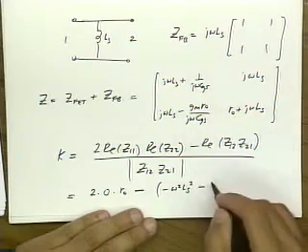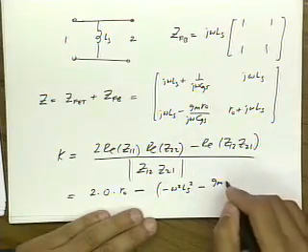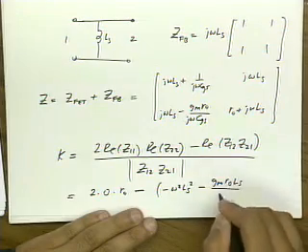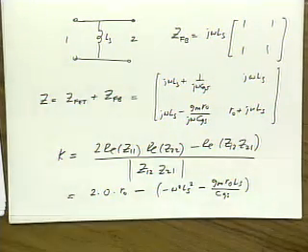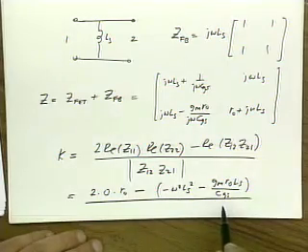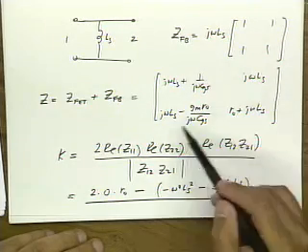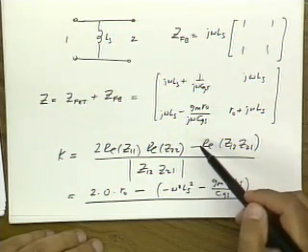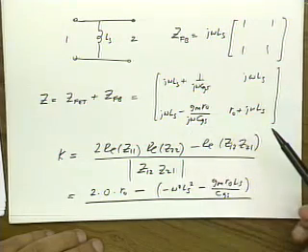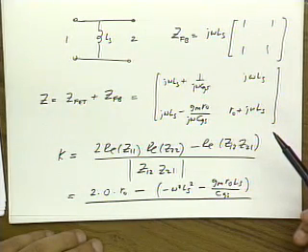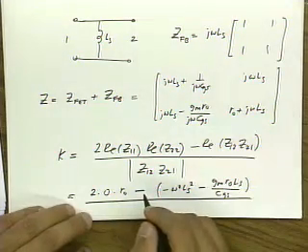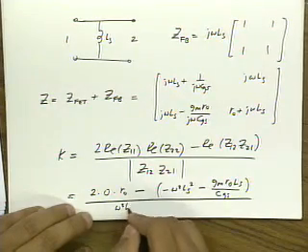So the second term gives me minus GM RO LS divided by CGS. And then on the denominator, I have the magnitude of this product. So it's basically the real part squared plus the imaginary part squared. In this case, if I multiply it out, it's all real. And I think I made a mistake in my notes. Whoops. Okay. So if we multiply this out, it's omega squared LS squared.